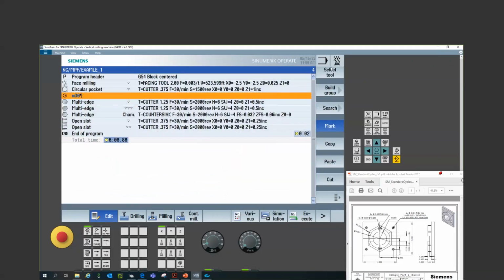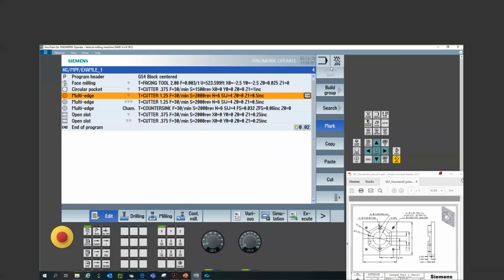I would think so. One trick I do, and I know you were probably going to show it later, is if you put sequence numbers in, you can use a go to command and jump over operations. Yeah, good point. But the problem with that is some of those operations, if they're needed, won't be machined because you're just jumping right over them. Right. Just another little trick you could do. I generally put numbers in after I'm through editing. I don't use the automatic numbering sequence because editing gets a little messy and I wind up having to redo it anyway. But yeah, that's a good point. I agree. Yep, for sure.